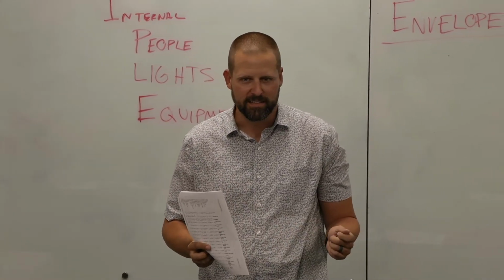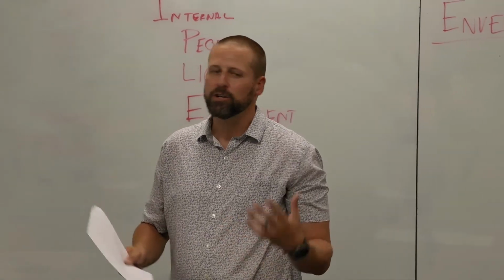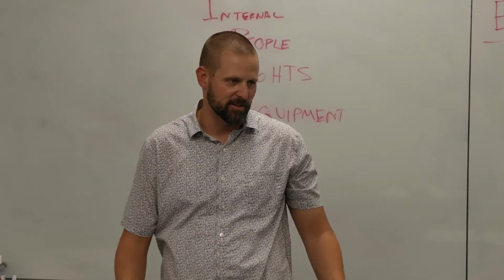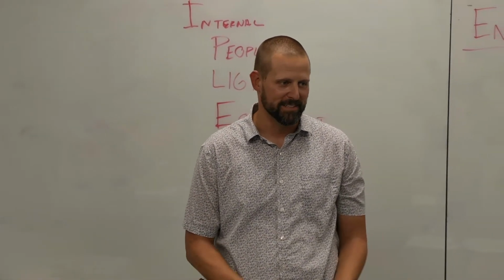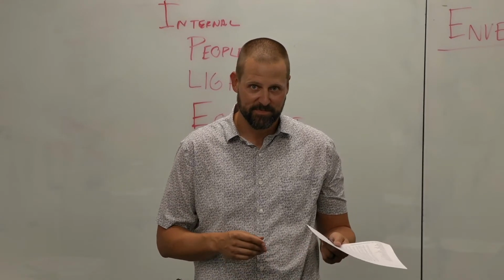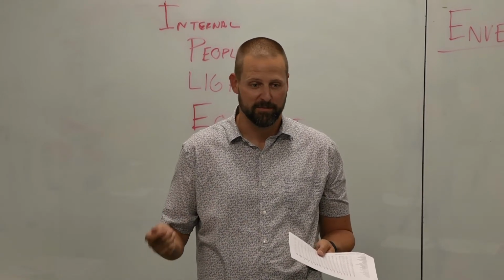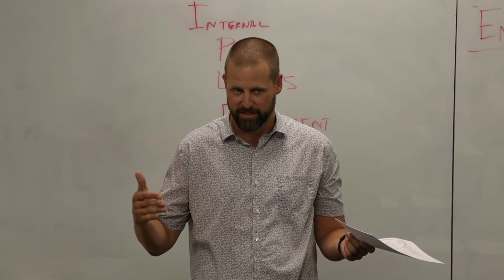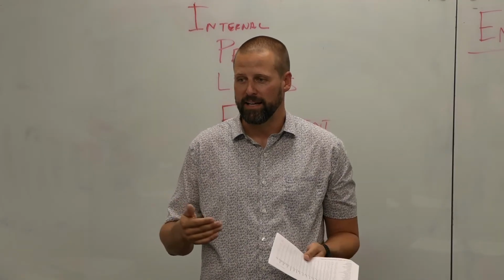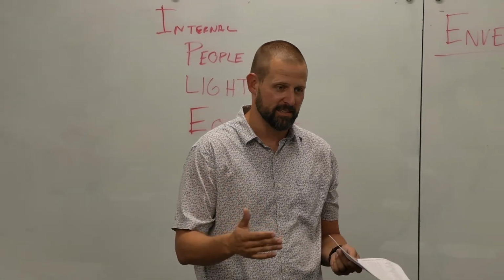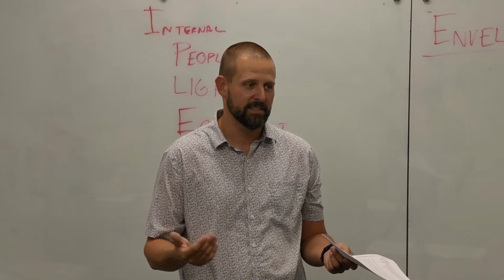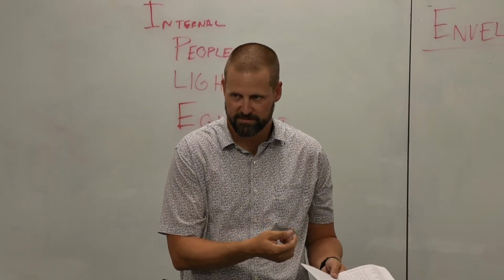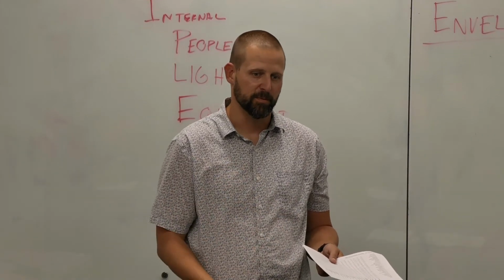Just something to keep in mind: weather's always changing. It's always getting hotter, it's always getting colder. We're going to complain either way. We need to anticipate what our customers need. For a commercial office building, it probably doesn't matter if it goes a little bit above these ranges. For a pharmaceutical business where they have to shut down a line if it goes above the humidity, we would add adders to some of these design temperatures. Like we'd add a few degrees one way or another.